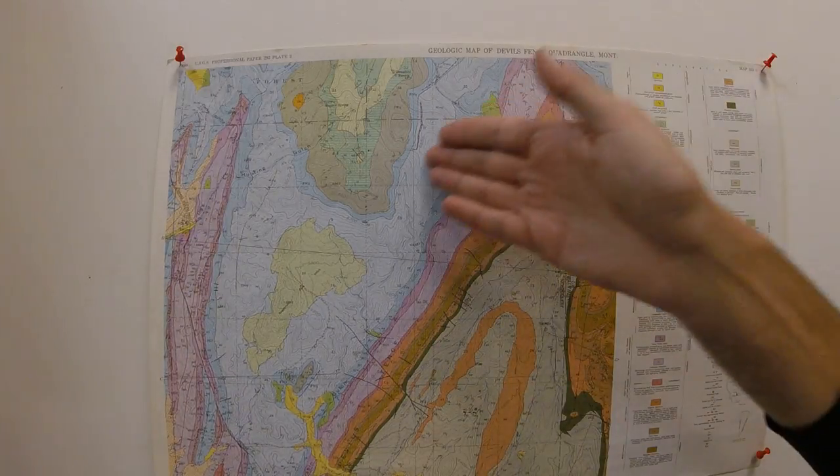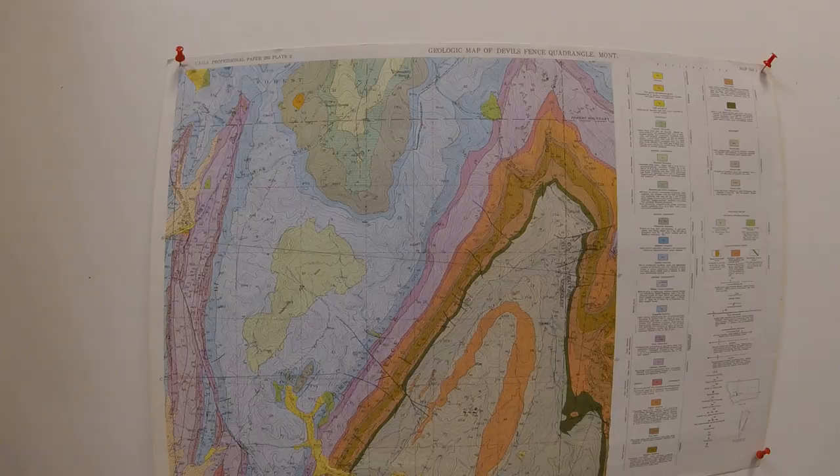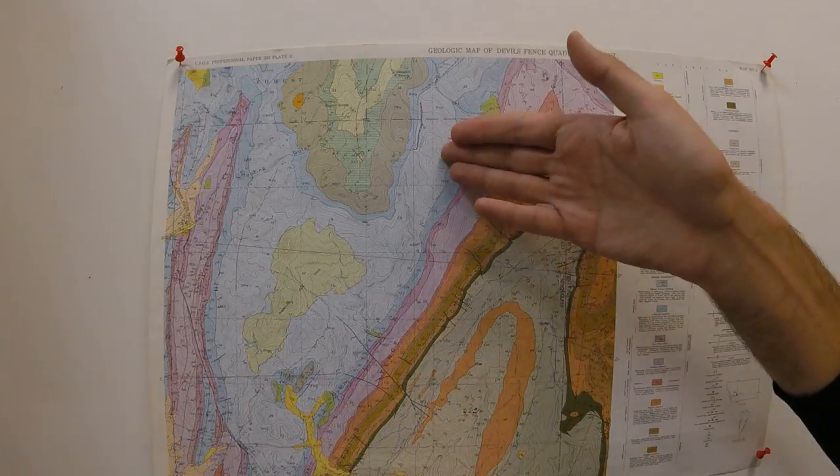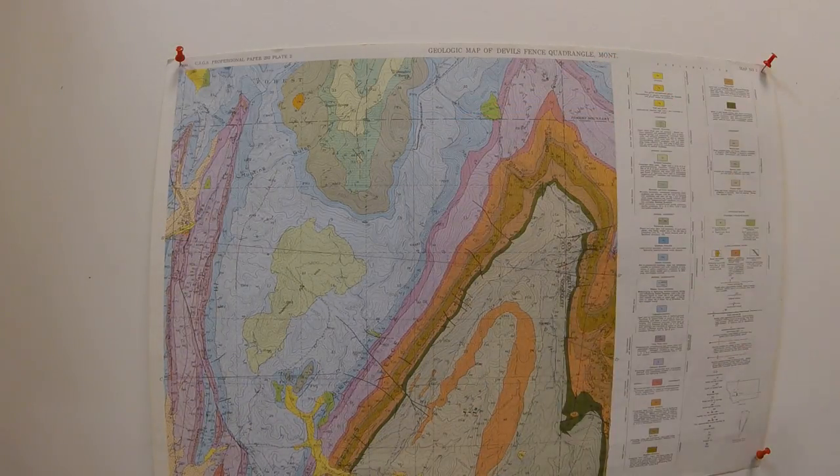And if, for example, you calculate that MMC cannot be more than 1,000 meters thick, then on your cross section you know that it cannot appear more than 1,000 meters thick. So that's how you make your section a bit more correct.